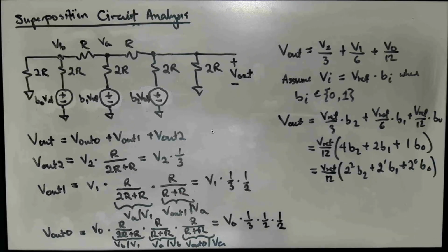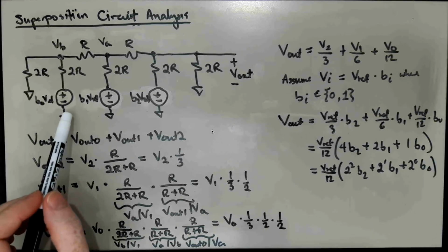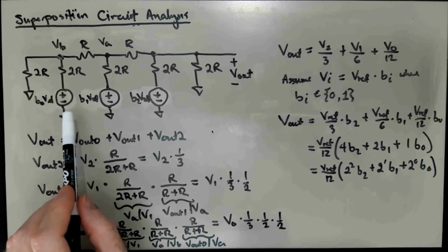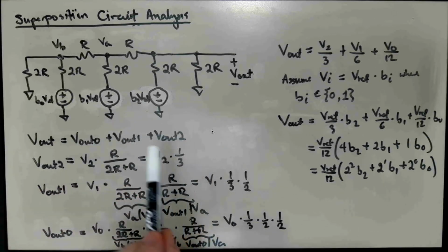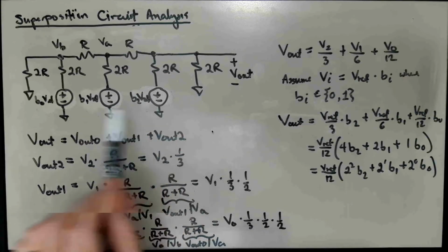This format of a DAC is actually very well suited to a situation where you have something like a microcontroller and you've got a bank of digital output pins that you can set either low or high, at ground or VDD, and you can often control all of those bits by writing a single binary number into a register, and those values are all asserted simultaneously.